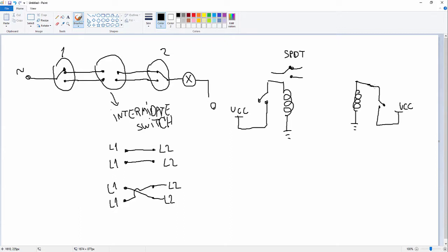Okay, so I will build a circuit like this. What I will do here is exactly what we are seeing here. So I will have here my SPDT. We'll connect this here and this to this side, this one to VCC, and this one to the lamp and to GND. This will enable me to do exactly the same, controlling the lamp with both relays. Of course, everything that we see here is the relay. This is one relay. This will be the second relay.